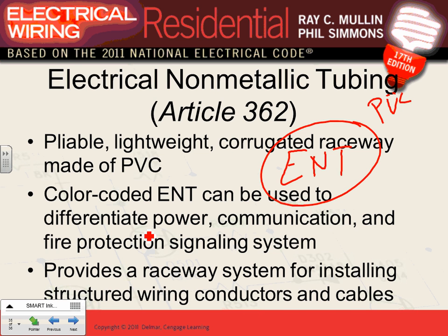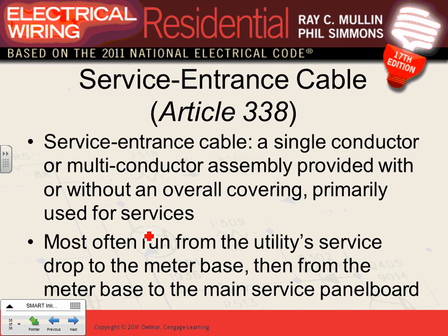So these are another option for you for wiring methods. Service cables, guys. We'll talk about this one. Show you a couple of things in service cables. Service cables typically bring power to the building. Sometimes we use them for branch circuits, for major equipment like ranges or dryers. But typically these are the cables, two cables twisted, coming to your building.